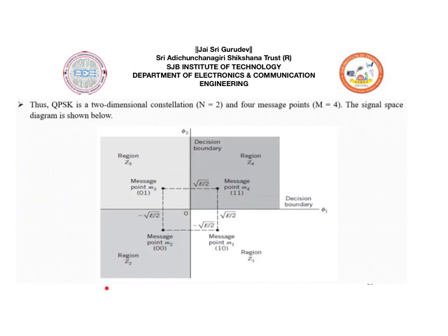Next, moving on to the region Z2, in which the second message point M2 is considered. It has d bit representation 0 0. This is the one which we have taken as S2 in the table. The coordinate values will be minus square root of E by 2 and minus square root of E by 2. These are the values pertaining to 0 0.